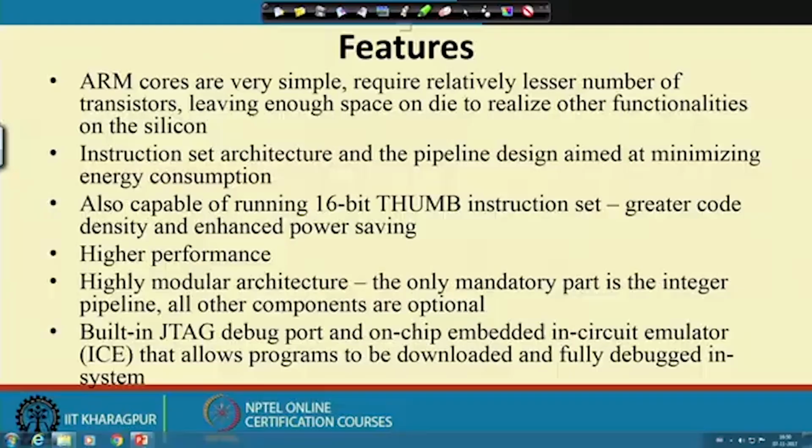So, there is a JTAG port. In fact, many of these advanced processors now have this JTAG port, that is for the debugging purpose, and we have got this in circuit emulator. This will allow programs to be downloaded and fully debugged in system, when the system is operating. So, you can take a snapshot of various registers through this ICE mechanism, and you can then try to analyze what the problem is. So, this is a very important feature when you are designing embedded applications using some development platform like some PC.